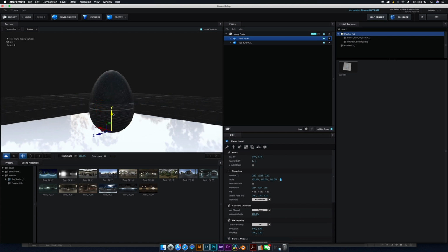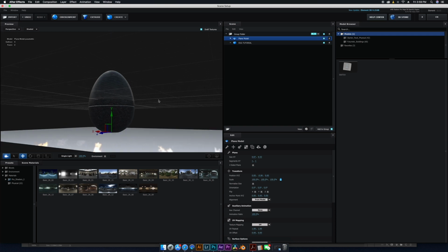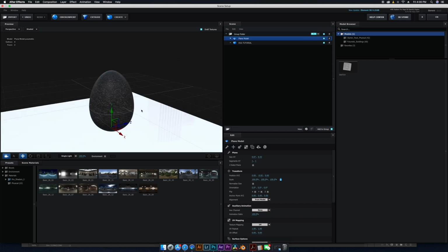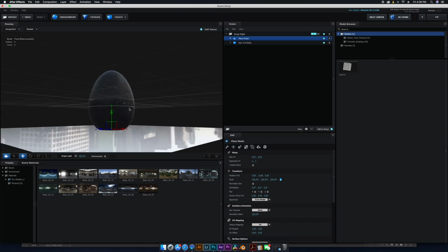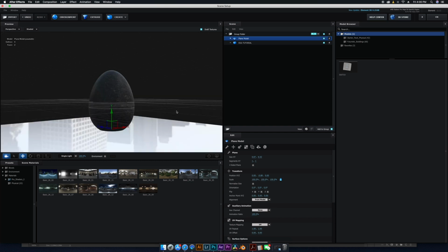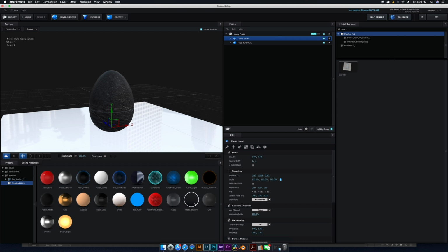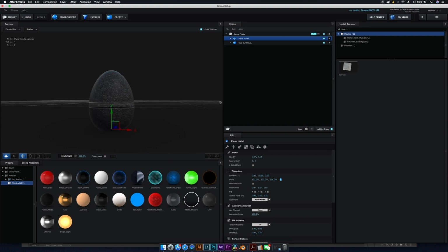And basically this is just a flat solid. I'm just using this flat surface as a shadow map for our egg, and actually brought it up a little bit to make it look like it's going through the ground. Go back over here to my materials, and we're going to select the matte shadow material and drop that on. And now we're going to hit OK.